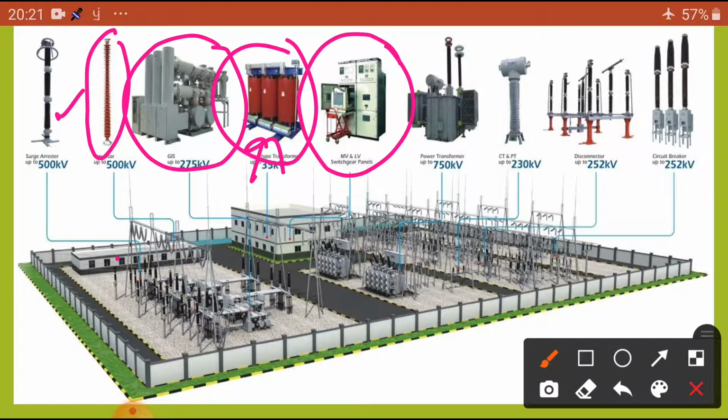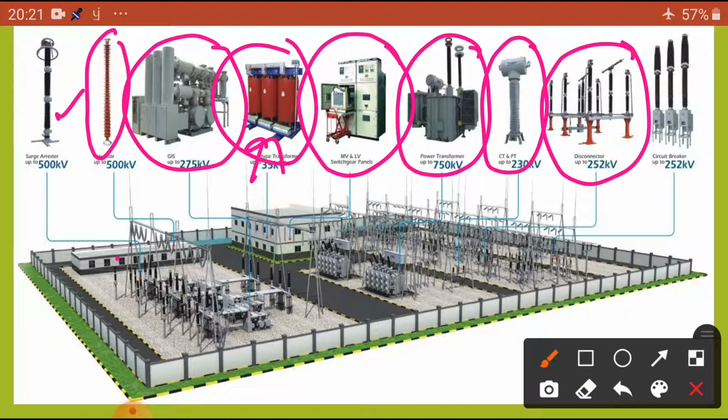And so you can see the PTR, the power transformer in a substation, is essential, where we are going to step up or step down. And you can see the instrument transformers, CTs and PTs. And you can see the isolators, the single break and double break isolators. Sorry, here is the insulator, and here are the isolators. And this is the circuit breakers. So for R phase, Y phase, B phase, each phase separately we require circuit breakers.